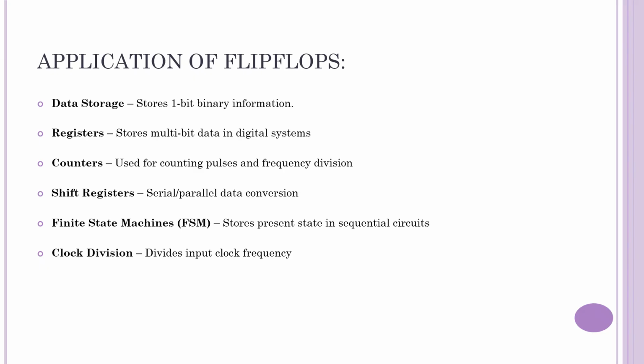Next, counters. Using T or JK flip-flops, we can design synchronous and asynchronous counters. These are used in timers, digital clocks, and even frequency division circuits. Now, let's talk about shift registers. Using D flip-flops, we can shift data left or right. This is super important in serial to parallel and parallel to serial communication. That's how communication systems move data efficiently.